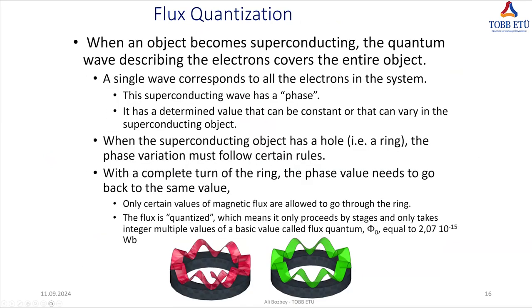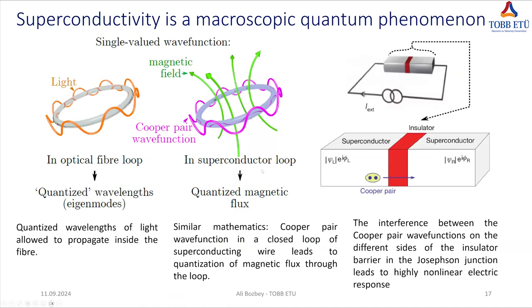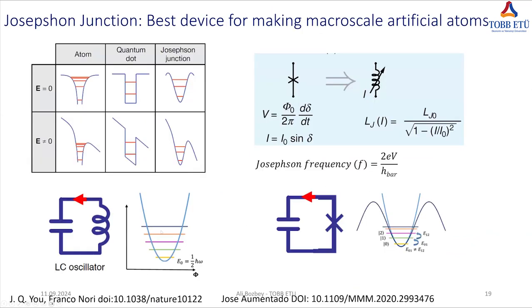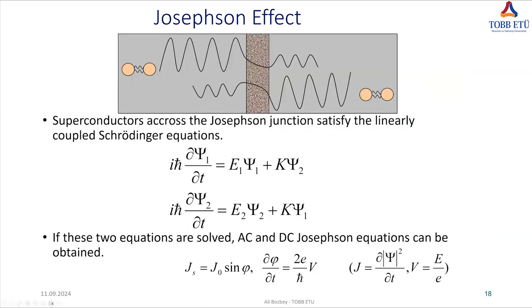For example, we use one flux quantization property to design a digital circuit, or use this non-linearity of the Josephson junction when we design a qubit or a parametric amplifier, or when designing a transmission line, we use the zero resistivity. Then you can design very high Q resonators.